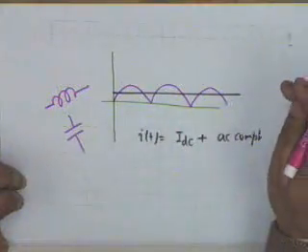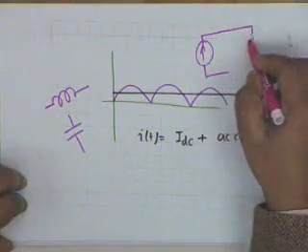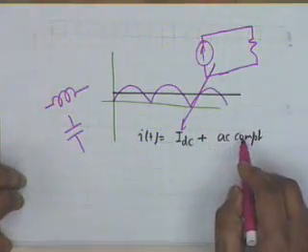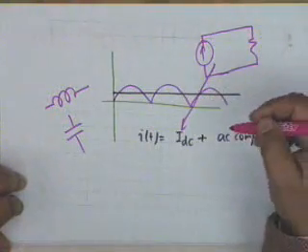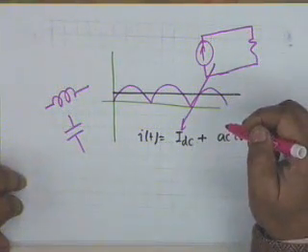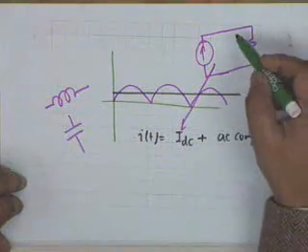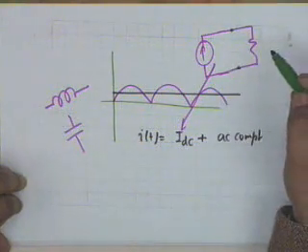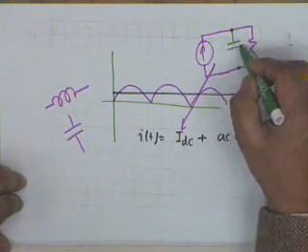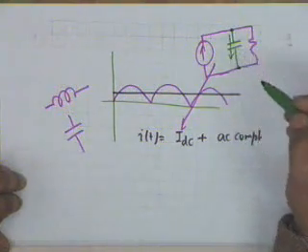All right. The idea is that if you have a current, let's say consider a current generator, this supplies a load, and this current consists of DC as well as AC. If somehow we do not allow the AC component to pass through the resistance, then obviously we shall do our job. That is, the basic concept is, if we provide across the load a 2-terminal component which allows only AC to pass but not DC, obviously that component has to be a capacitor. So as far as AC current is concerned, the AC component passes through the capacitor.